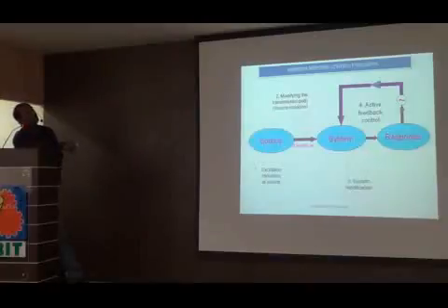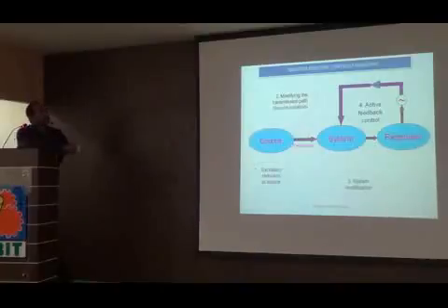And then there is a fourth option available, but we are not using it, or we can't use it in a way. That is, you try to read the response and send an opposite signal so that you get an active feedback system. To have an active feedback system, you should have some generator also, which can produce a signal. So you know the signal strength and the phase. You produce exactly the opposite signal onto the system. Now both signals will get nullified, so you will not feel the response on the system. Means the vibration levels you will not feel.